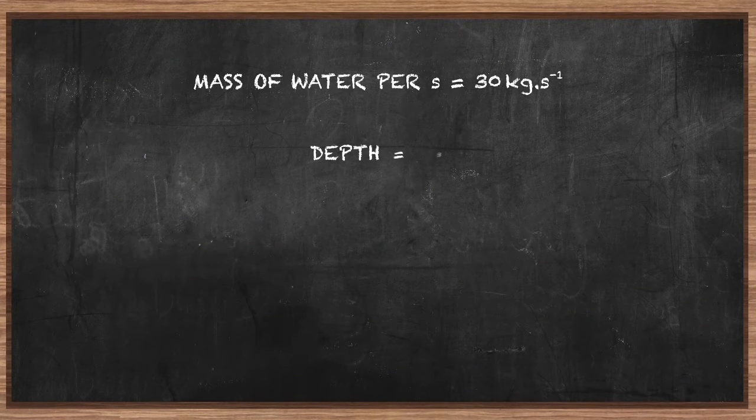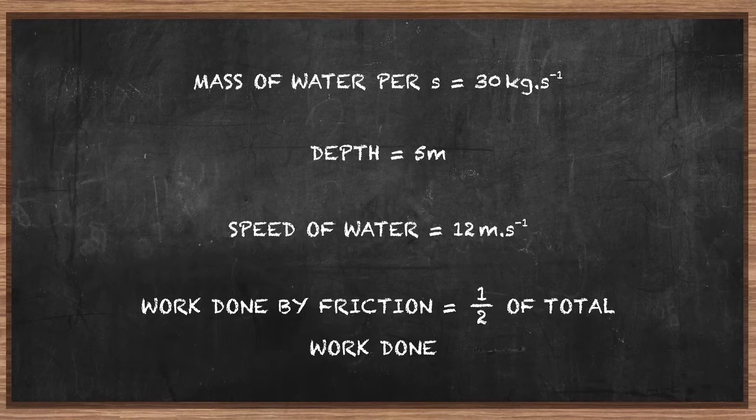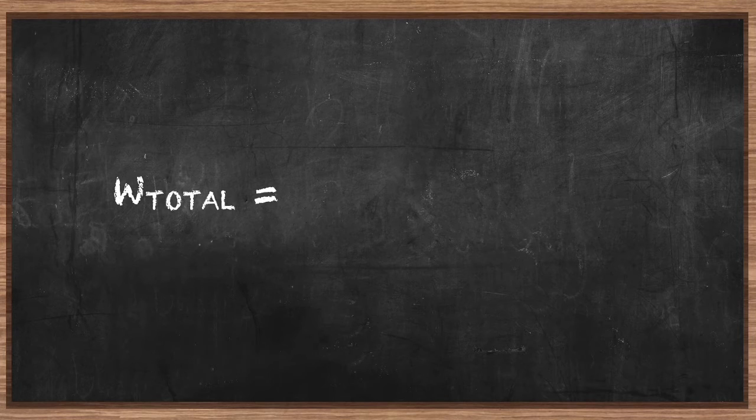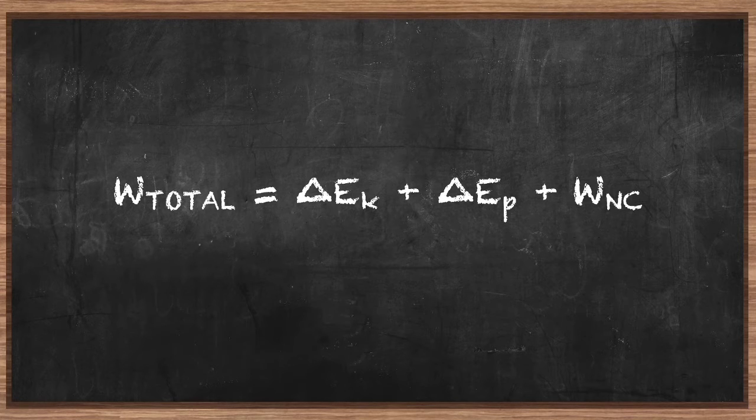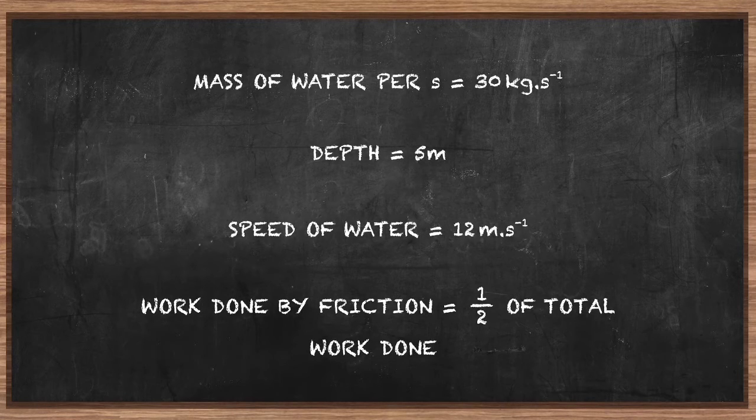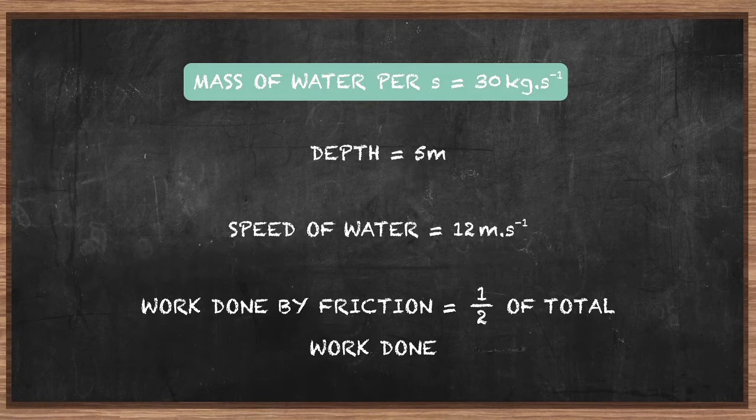Let's review the strategy we used to solve that problem. Number 1, we organize the facts. And number 2, we wrote down a formula to help us calculate the total work done by the pump. Looking at the facts, we realized that we were given the mass pumped per second, so we set about calculating the change in the kinetic energy per second, and so on.